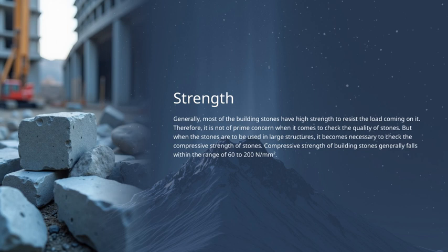Typically, the compressive strength of building stones falls within a range of about 60 to 200 newtons per square millimeter. So, understanding this range helps us select the right stones for the right application, especially in substantial constructions.